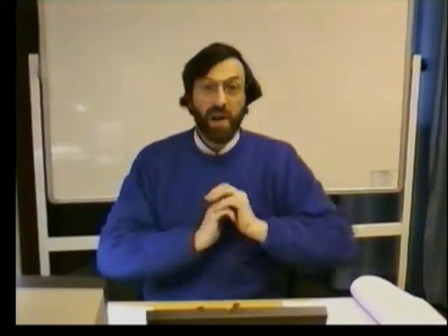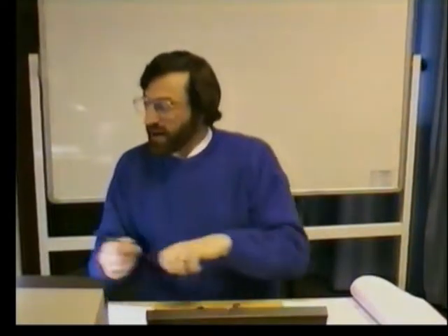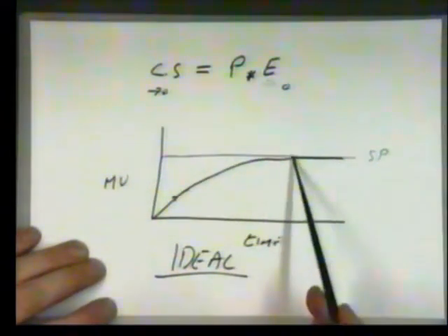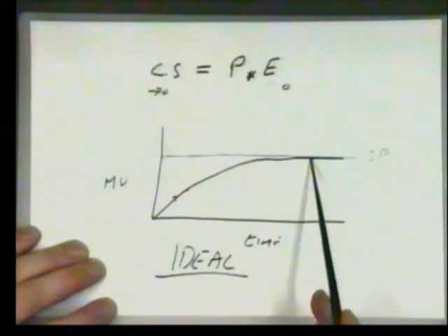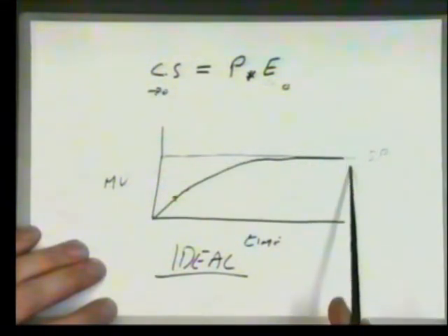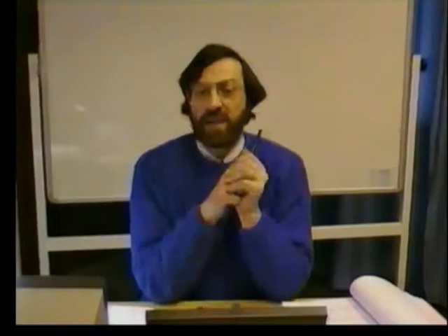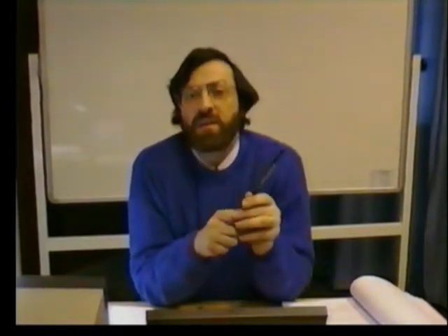You always get perturbations. In a machine tool, whatever you can do, you can't do anything about it. You've positioned it beautifully, but there's always vibrations somewhere that move you off station. So you always have a whole load of extraneous effects outside of your system that are pushing you away from where you want to be. So even though in our ideal system we are hitting our set point, outside events keep on knocking us off of it.